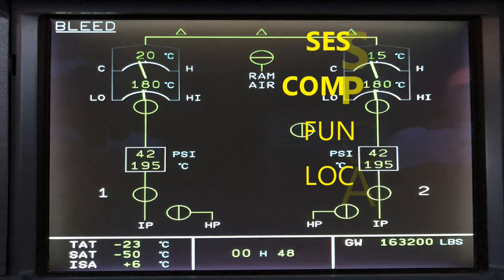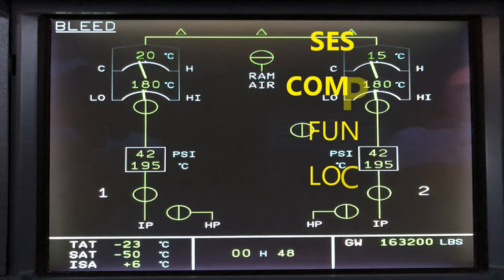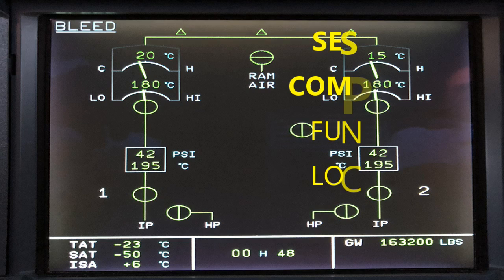All right, so what happens when the pilot pushes the APU bleed push button switch? Say you're doing this on the ground for maintenance, and you push it to the on position. Then that's going to trigger a signal for the PMCs to send a ground signal to the ground bleed auto control relay. And it's going to do it if you have the APU bleed load valve in its full open position.